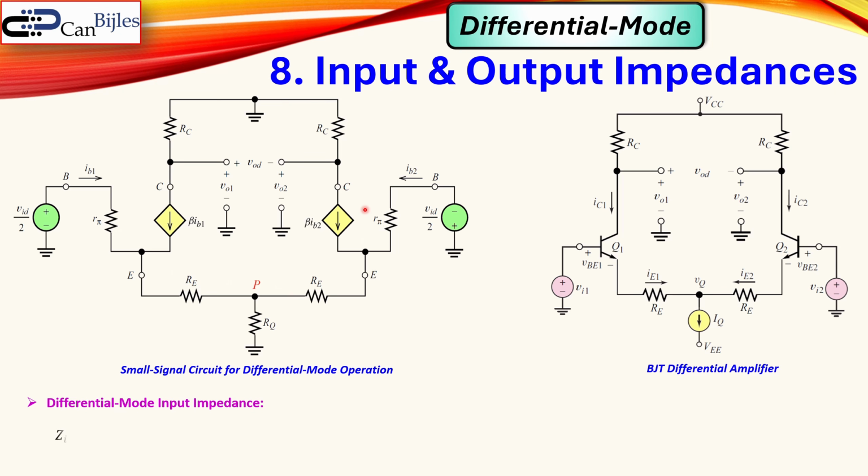That means I have now here the condition, which is then defined as the impedance Z input for differential. That is the ZI of VID over IB1, which is actually this current. Now, well, that means then it is 2 times the R pi. Of course, this is then beta plus 1 times larger. And I have it actually then 2 times because I have it again here. That's the expression for the input impedance for my differential mode condition.